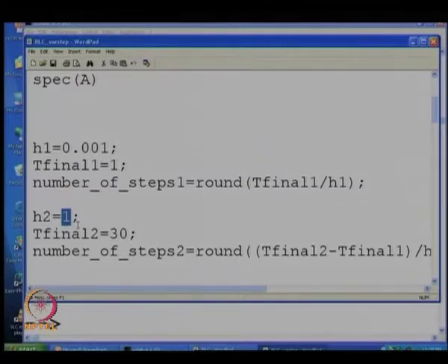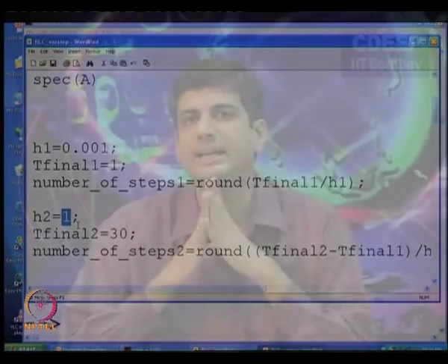The key to this, of course, is that often when we are simulating a system, we know something about the system. So, that is one way you can use your engineering judgment and come to a conclusion about what time steps to use, or you can do a bit of trial and error. But most industry grade programs will actually have some way of estimating the truncation errors at every step, and if the errors are not too large, then they may even permit adaptively to start increasing the time steps.